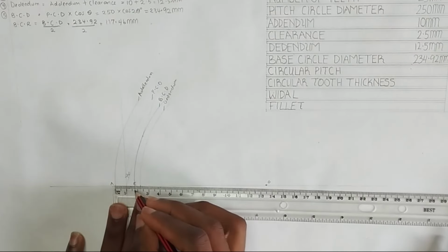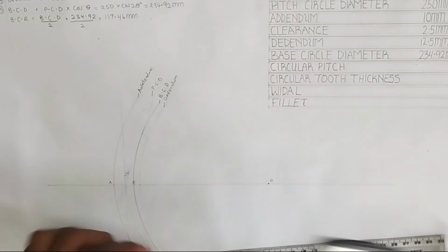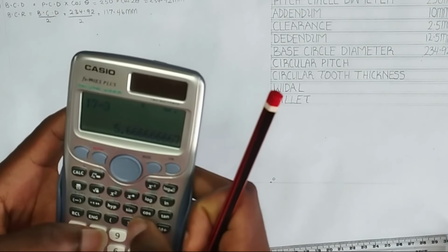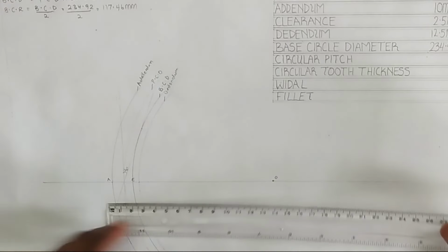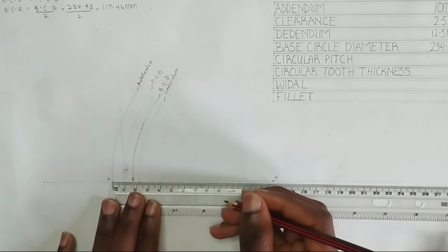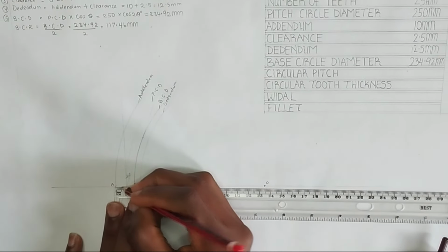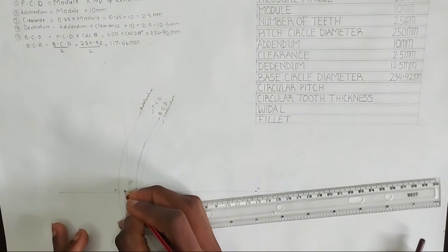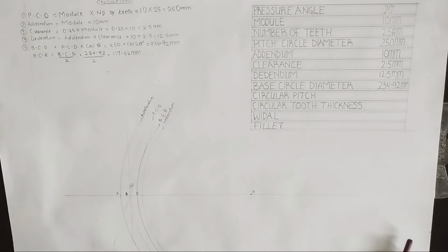We have been given AE as seen here to be 17 millimeter. So I'm going to pick 17 divided by 3. That's going to be 5.67. We are dividing it in 1:3, so that 5.67 is going to be around this place here. This place I'm going to label as my point B.